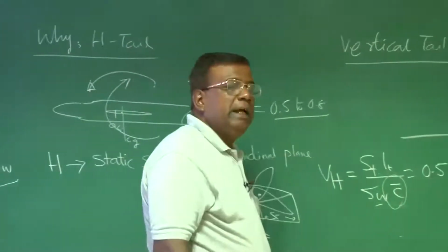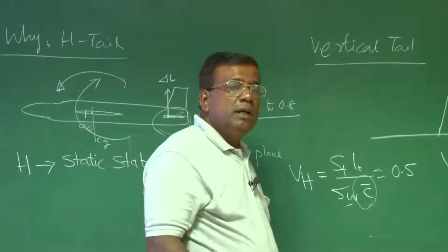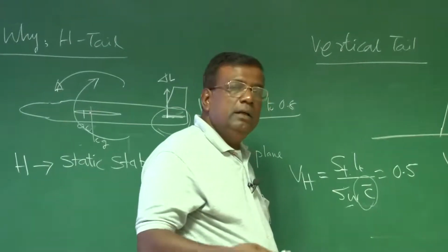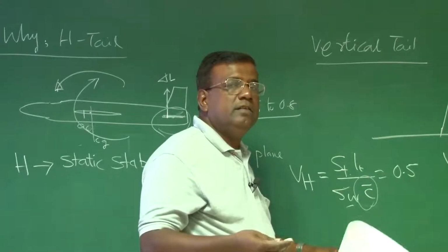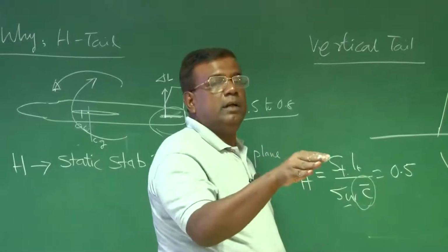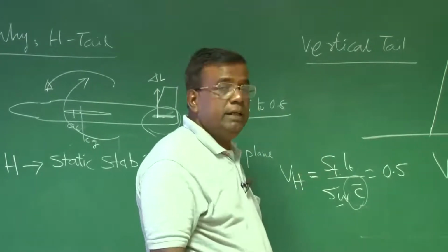So you don't want to make an airplane highly sensitive. If we go on increasing the vertical tail, then if it becomes highly directionally stable, it becomes very sensitive to wind. Any wind, immediately it corrects. This frequency increases. You may not like it.